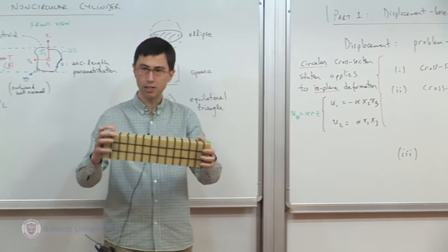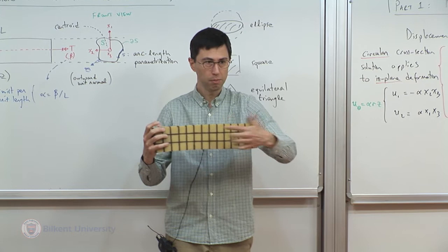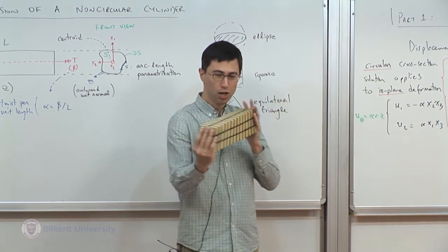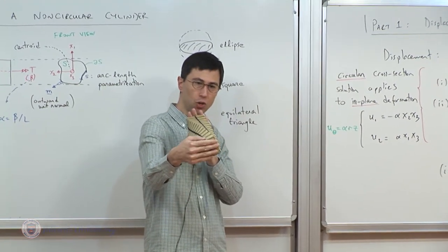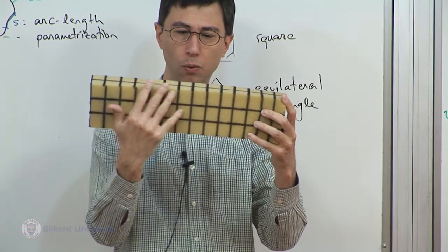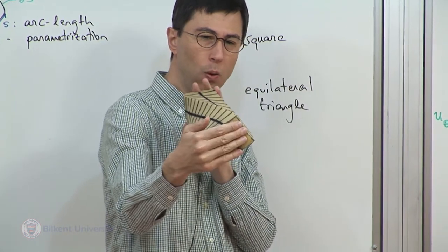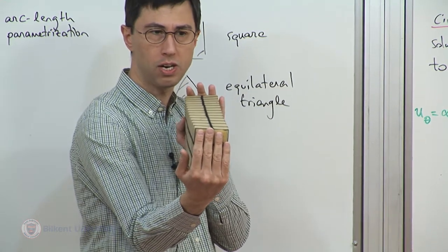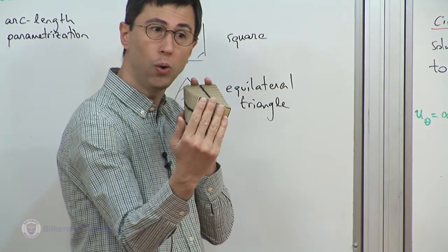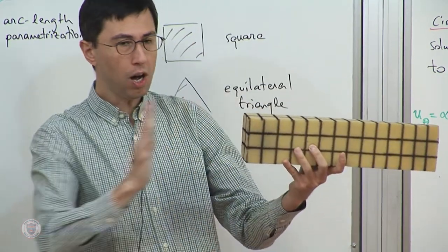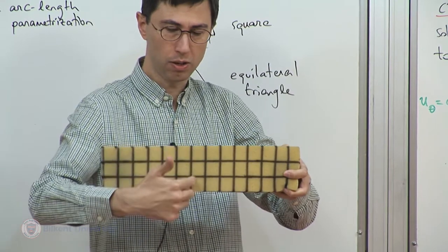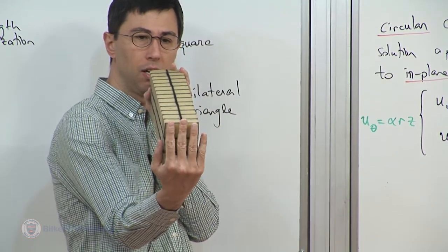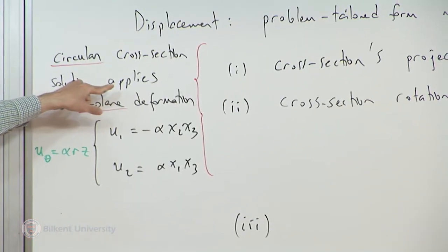because there is a displacement in the axial direction, which you see from the displacement of the black vertical lines, right? Okay. So now, however, Saint-Venant proposed the following at the time. If you look at the cross-section from the front, and as you rotate this cross-section, yes, a lot of things happen when you look from the side. But when you look from the front, he proposes that, well, maybe the cross-section not only rotates, perhaps it distorts a little bit, but to a very good approximation within the limits of linear elasticity, so small deformation, he proposed that the cross-section only rotates still. So if you look from the side, there is an out-of-plane deformation of the cross-section, indicated by the deformation of these black lines. But if you look from the front, and if you don't see the third dimension, you still see this rectangle only rotating, just like the cross-section of a circular cylinder.